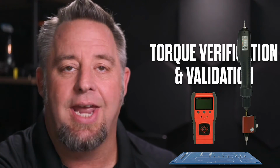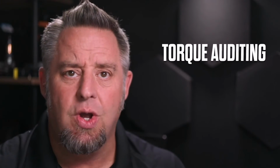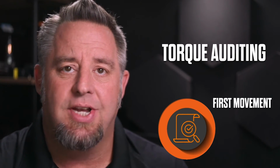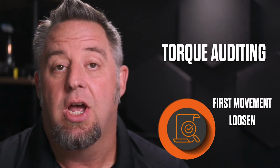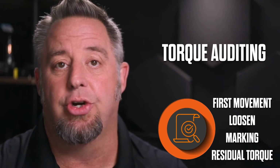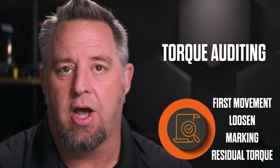So let's take a look at what we would be doing after the assembly process and what types of tests we can perform at this point. And so with the after or torque auditing process, we can do tests like a first movement test. We can do a loosen test. We also can do a marking test. And all of these may fall under the term of residual torque that you may hear when you're doing some torque auditing after the fact.